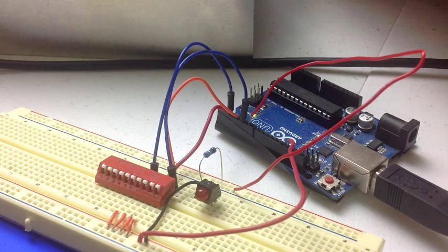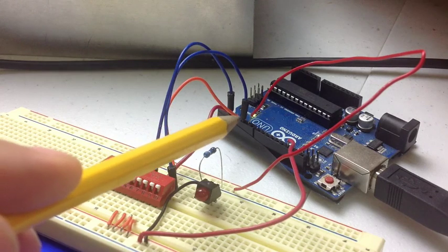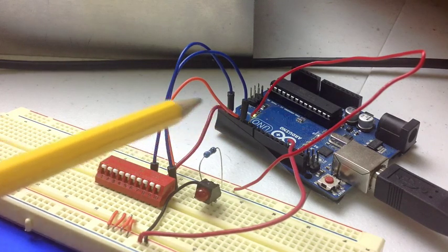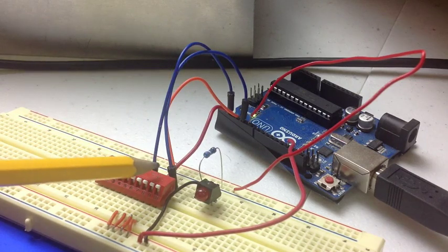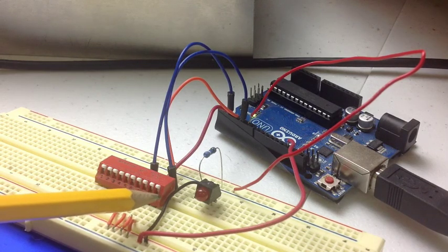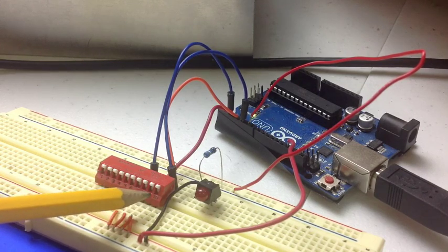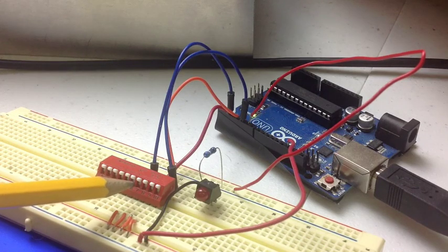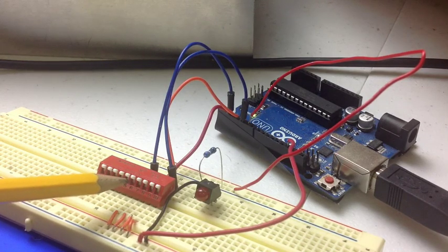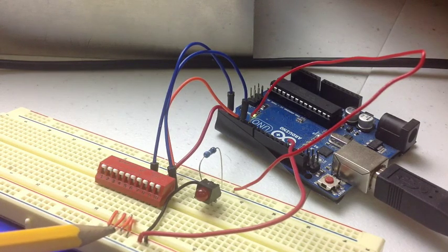This is the hardware that I'm using for this project. So for this project, I have my Arduino, and I'm taking pins 2 through 5 of the Arduino, and I am connecting them through wires onto my breadboard. And on the breadboard, I'm connecting to this dip switch, dual inline pin switch. This particular one that I have has 10 pins associated with it. The important thing is that I can easily switch multiple pins at a time. And so they go through the switch, and then these guys are for ground.